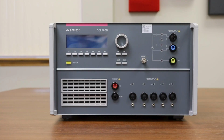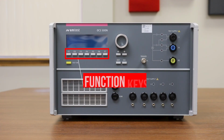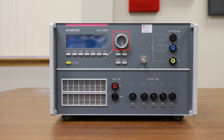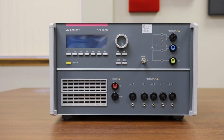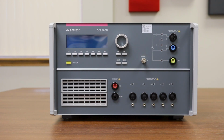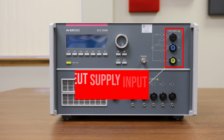Now we're taking a look at the front of the unit. Starting in the upper left corner, we have the display, and just below that are function keys as well as the yellow test on button. As we work our way right, we have the turnstile, cursor keys, as well as the exit and escape buttons. These are going to allow for the user to navigate through the different menus and select different criteria. As we continue right, we have the trigger output. Next to that, the coupling path LEDs and our EUT supply input connections to the coupling decoupling network.